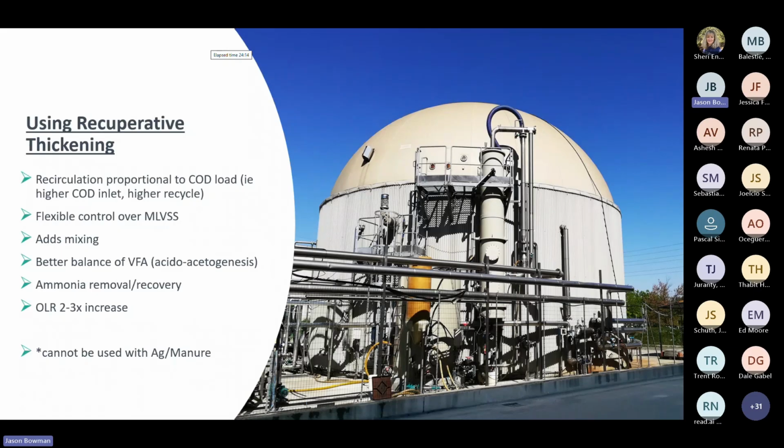So as with activated sludge, as an example, this specific recirculation to this digester unit ensures a healthy, stable, but also a diverse population of anaerobic bacteria are being returned. So this helps provide additional balance or buffer or stabilization to ensure that your acidogenesis and your acetogenesis steps are balanced and that your VFAs don't run rampant in one direction or another.